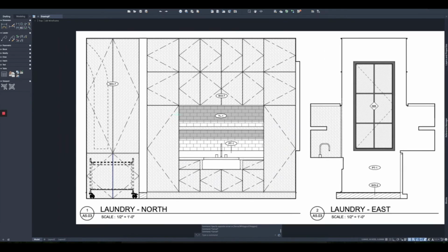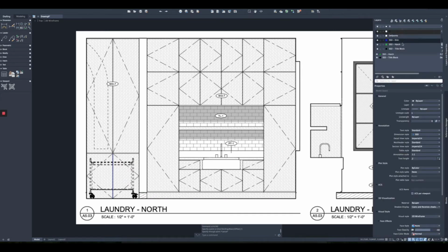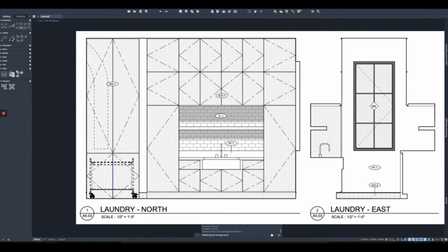So the first thing that we need to do is we need to get this larger, up to full size. So what I like to do is strike a construction line that isn't white, because white's difficult to see on a white PDF. Basically, you just drop it at the floor line. I'll drop another one at the countertop height.